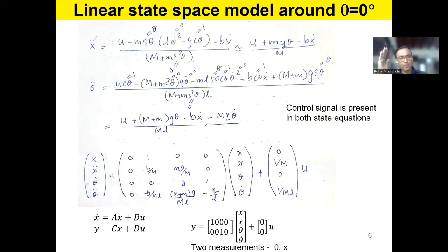Okay, now this is very important. It is just a single control signal that you can use to control two variables in the system, theta double dot and x double dot. But remember, this statement is valid only when the pendulum is at a vertical, nearly vertical position. Okay, if it goes like that, all of these statements that I'm making here are not valid.